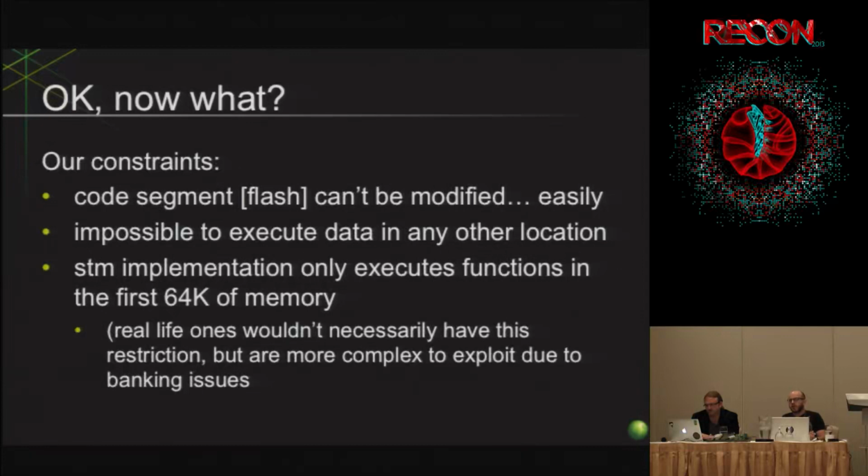But 64K, even though it's small, still usually will have enough of the stuff that you care about, especially in a ROM scenario where, if you are the manufacturer, you're coding this thing to allow you to update it in the field. Well, that's the exact code that you're going to put in that first block, right? It's going to be right in that very first page because, one, you want to protect it from being accidentally overwritten during your upgrade process. But two, it'll be accessible via these types of things. There are other limitations that just don't want to deal with banking. And that's why the first few pages are important, and why they allow you to protect them differently than the rest.